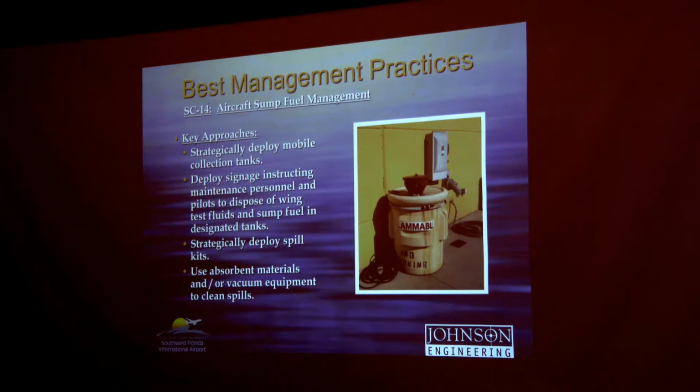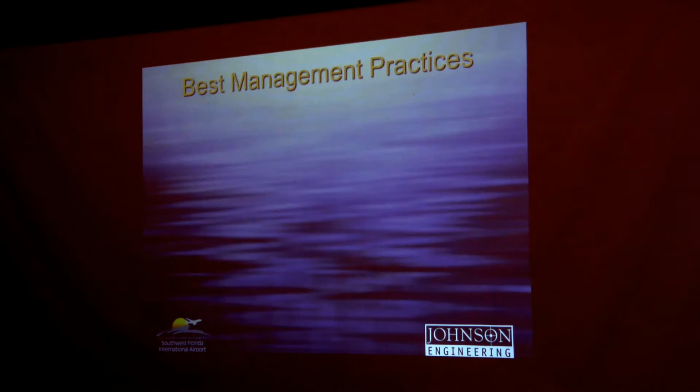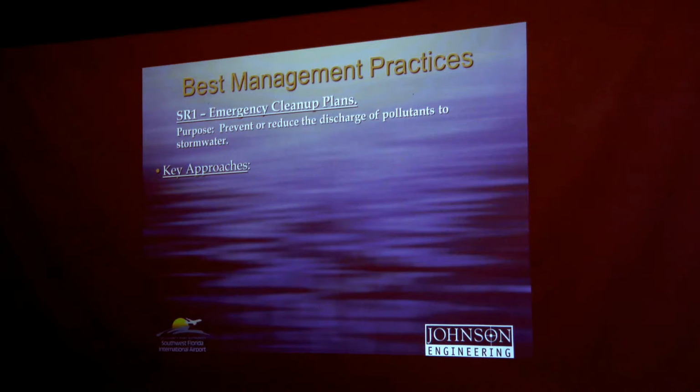All right, SC14, aircraft sump fuel management. Key approaches here include strategically deploying mobile collection tanks, deploying signage instructing maintenance personnel and pilots to dispose of wing test fluids appropriately, deploying spill kits, and using absorbent materials or vacuum equipment to clean up spills quickly.